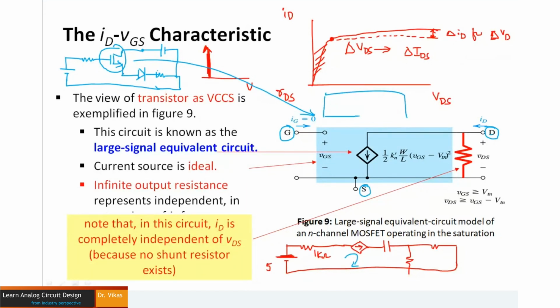If I say again the MOSFET here, it is between source and drain only, right? Between the source and drain the channel is there, and after the pinch off the channel gets tapered. That means whatever you are observing, a small resistance that is being observed, it is in the saturation region and it is between drain and source.